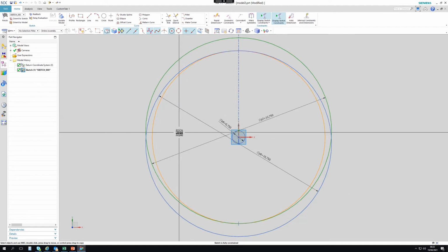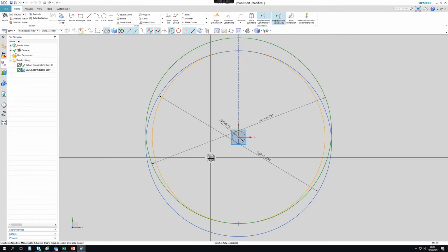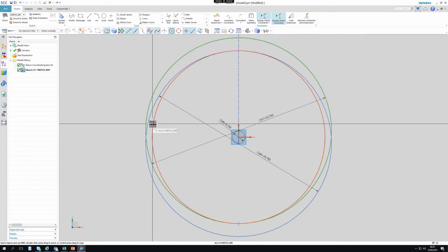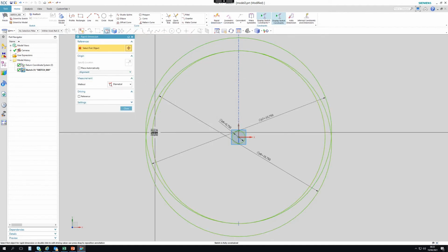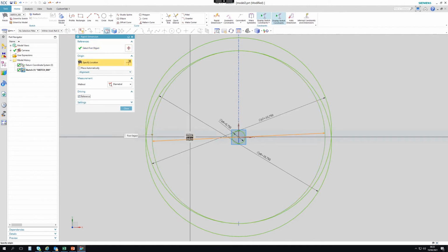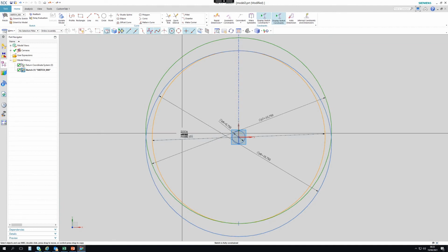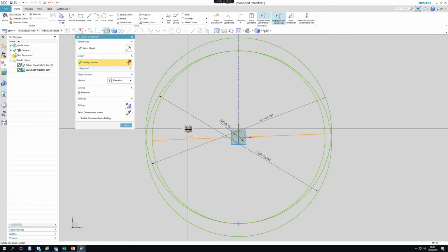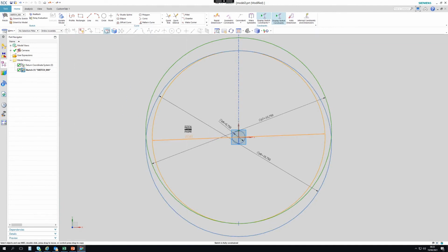And because positional tolerances are theoretically exact, if it works on this scenario, it works on all holes. So let's see what size this particular hole is. Let's put the diameter in. Let's make it a reference. Right, let's just make sure it's not rounding. It's Alt 4. Yeah, so it's not rounding.